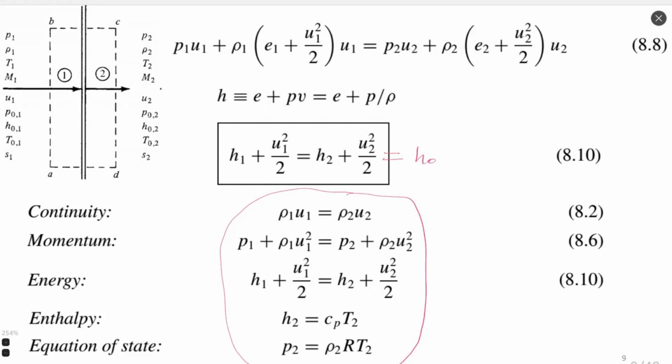It means that the equation system we just obtained can be valid not just for the case of a normal shock wave. It can be valid also for isentropic flow, or anything that happens inside a rectangular volume when we have just input and output and do not know what happens in the middle of this control volume.